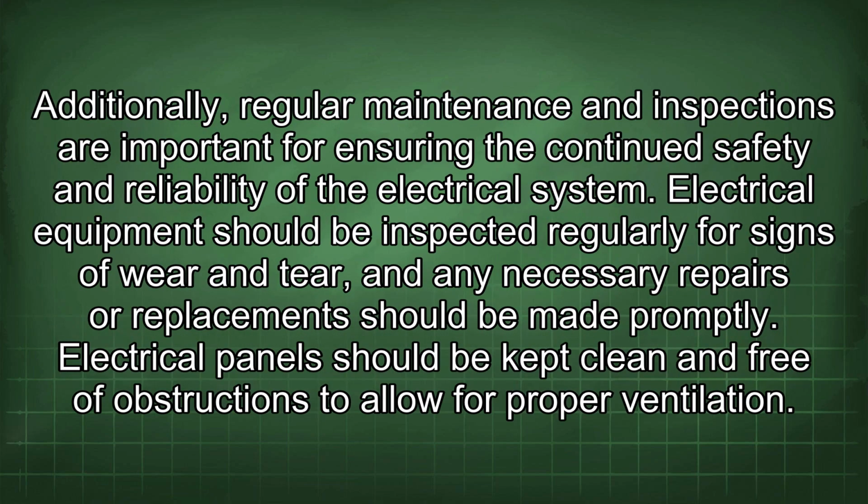Additionally, regular maintenance and inspections are important for ensuring the continued safety and reliability of the electrical system. Electrical equipment should be inspected regularly for signs of wear and tear, and any necessary repairs or replacement should be made promptly. Electrical panels should be kept clean and free of obstructions to allow for proper ventilation.